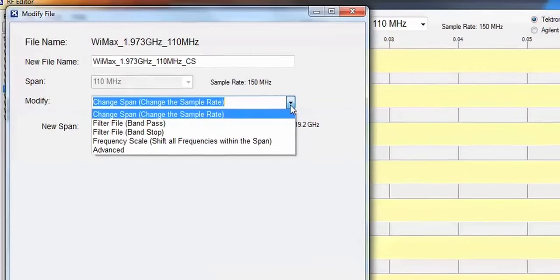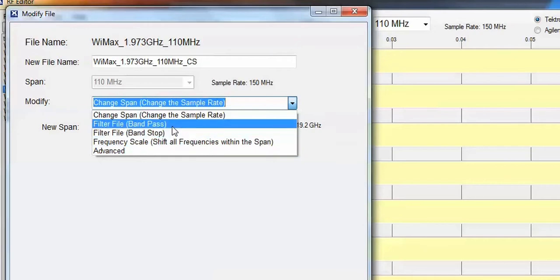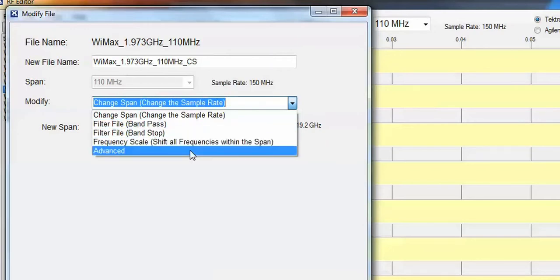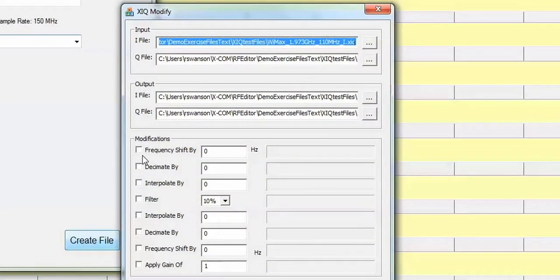Three operations, and I can do that within SpectraX very quickly by going through what's called an advanced modification. I could do things one at a time. I could go ahead and shift, then filter, and then shift, or by going into the advanced mode, I can go ahead and frequency shift by minus 27 megahertz, apply the filter, and then shift back up by 27 megahertz again.